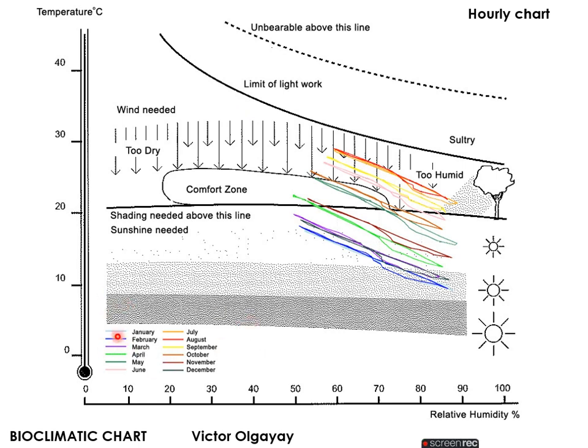Now you can see some charts, like January, where the points fall across day and night, and vary for every hour. We have about 8,760 hours, so we have to plot about 8,760 hours of points so that we can understand an average value of how many points fall under the comfortable zone, maybe 3,000 or 4,000 hours. So in this climatic zone, people can feel comfortable for about this many hours.